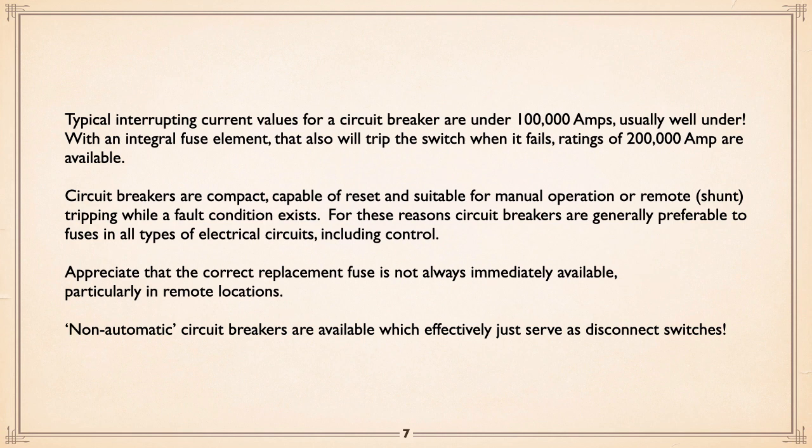Now, circuit breakers, the interrupting capability is usually under 100,000 amp, usually quite a bit under. And I'll make the comment that for most applications, pump stations and whatever, the fault currents, and there are ways of calculating them, I won't get into it here. That's your homework, figure out about fault currents, maximum fault currents. But you can add a fuse to a circuit breaker, which is kind of a hybrid, and then you get your high interrupting.